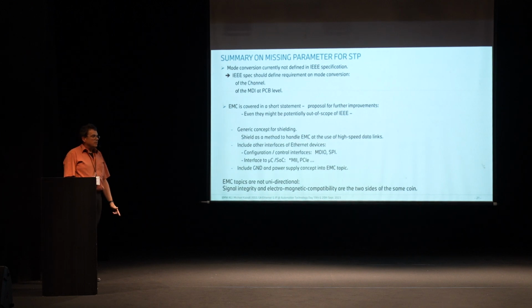And we should also think about ground and power supply, because when you think back to the presentation given about 2021, the shield concept does not eliminate all other problems just by having a shield. So I think ground and power supply also might be a topic for getting the EMC problems tamed.